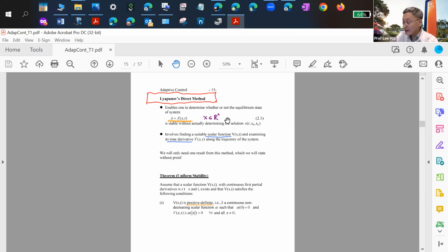My students will remember that. Yiming, Haipeng, Xiaoxia, Jialun, Li Chen, Yibo, then Ziwei, you will remember I said this so many times. Your state variables must appear on the right-hand side, no derivatives. Then the same signals must appear on the left-hand side with the first derivative only. This is what state variables is all about.